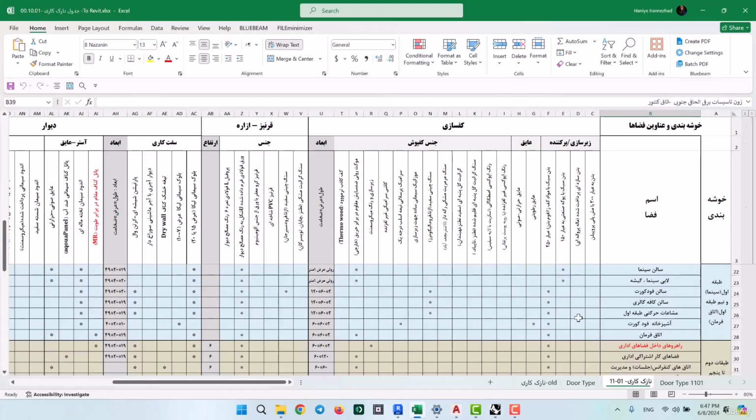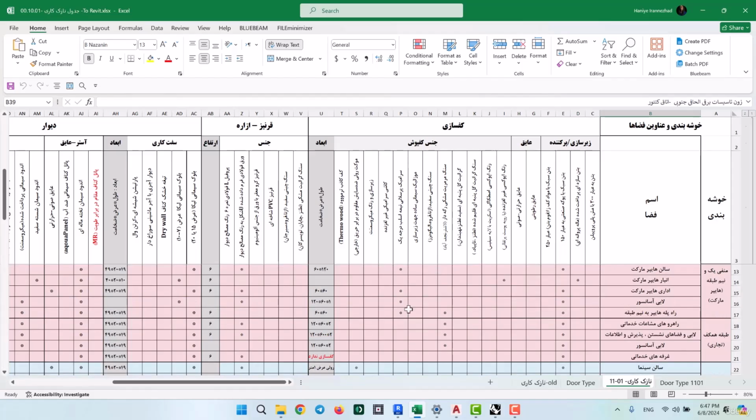Also, over here for this stone type that we have made, we put 2 centimeters for thickness, which is just the thickness of the stones. This 2 centimeters is only the stone's thickness, whereas you need to also add the thickness of the foundation to that value. So for example, all of them together would be 10 centimeters. Now for example, for the service corridor branches, it says the foundation needs to be a light concrete with industrial pumice. Okay, so we know that we need some fillings beneath the stones.